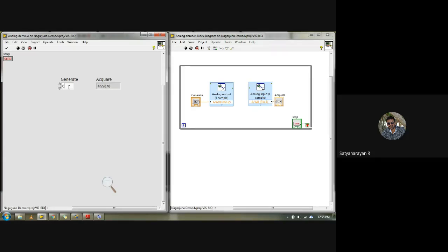That's not an issue. You can see here the voltage range will be from 0 to 5 volt. Whereas in your myDAQ, the analog input, since it was a differential thing, was giving -10 to +10. But here, if you give 10, the maximum output you get is 4.99. Even if you try to give a negative voltage, it's not considering the negative voltage, because the connection we have given is single-ended. Single-ended can only generate from 0 to 5 volt maximum, but differential can persist from -10 to +10. That is the only difference.